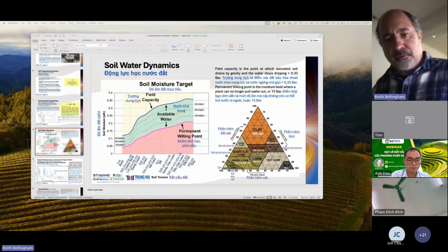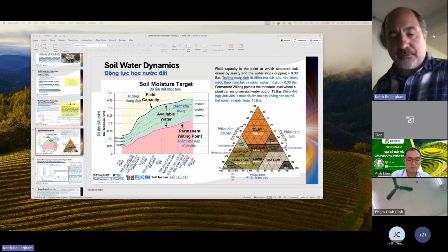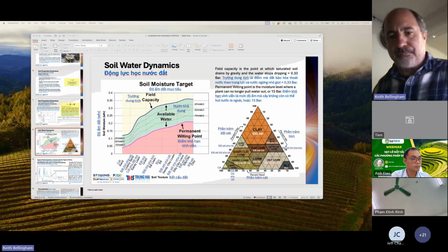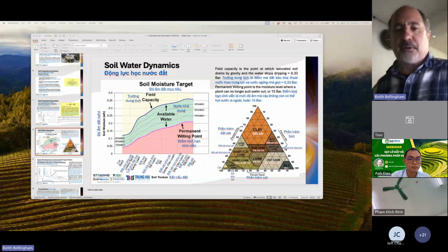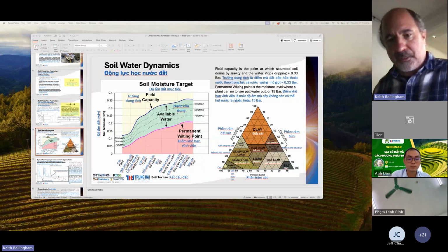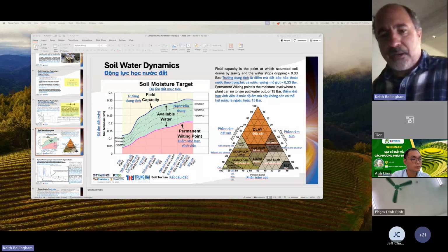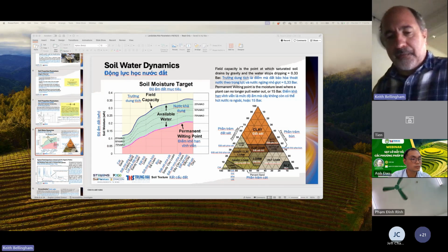Rainfall, soil moisture and the extensometers are the parameters that can be logged in the field in real time. The other static parameters like slope and vegetation are all characteristics of the site, whereas the loggable parameters would include the soil moisture, the precipitation and the extensometers. And again, the formula that would take all of this into account would have to be developed, and it would have to be weighted appropriately.